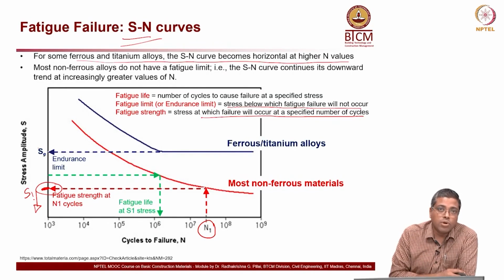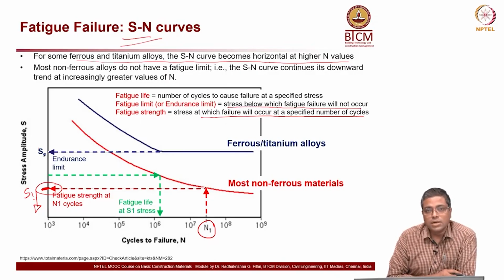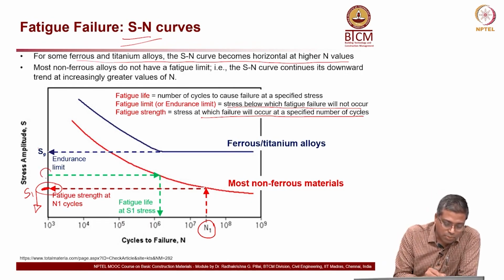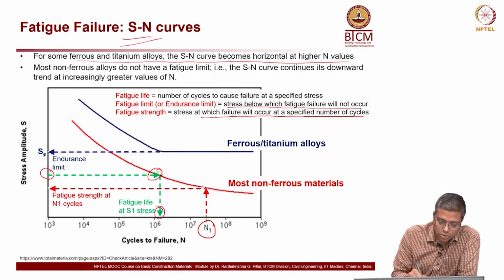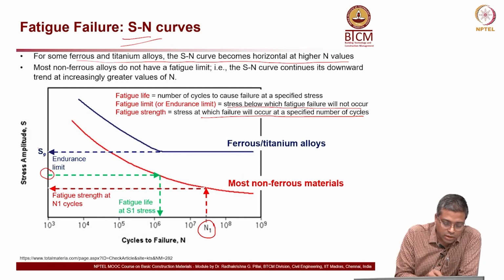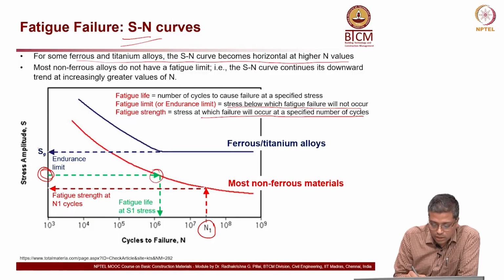Now, let us say you are talking about a bridge or any structure which is already built, and maybe there is an increase in the load or something. So, you want to assess the remaining life of the structure. What do you do? You know the stress which is applied, that is known. In the green case here, the stress is known, and I look at the change in the direction of the arrows. Okay. So, you go from here to the right and hit the curve and then come down.